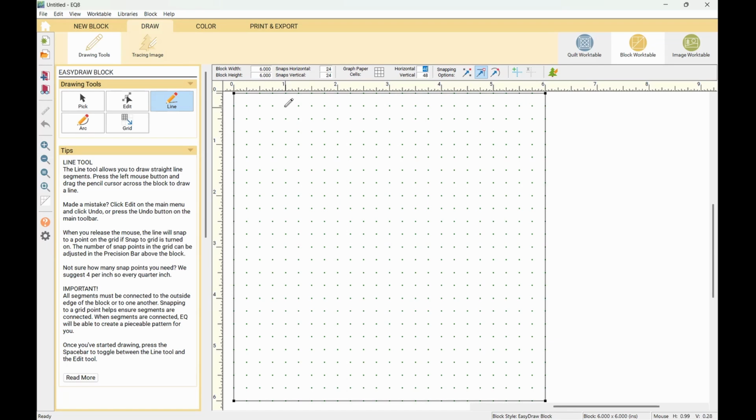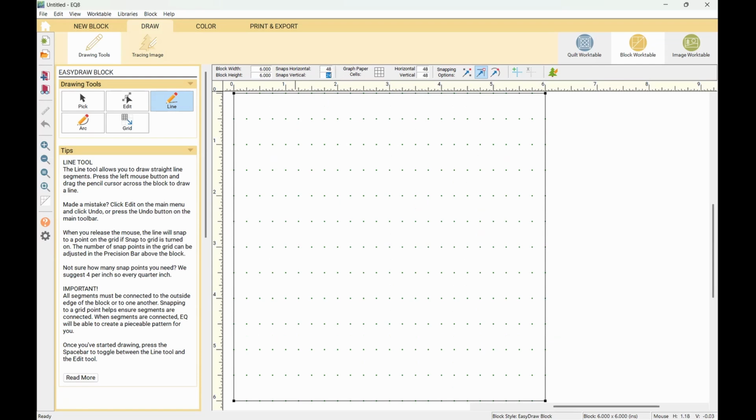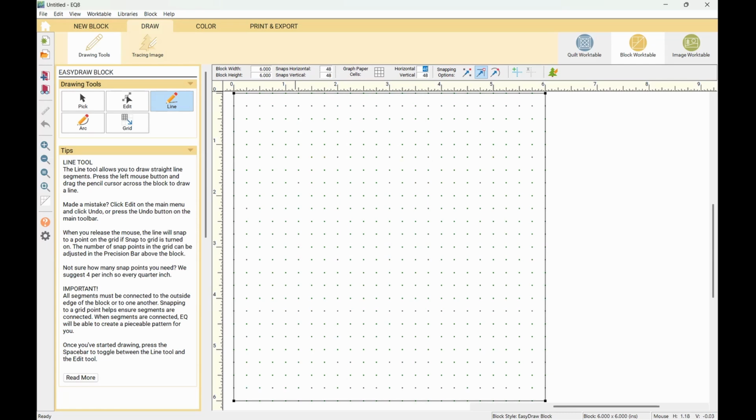And then if you have made it for more, like if I go twice as much, I go to 48, you still see what looks like 24 snaps, but there are hidden snaps on each of the 1/8 inch now versus the 1/4 inch. And it will snap, if you turn on your snap to a specific place, it will snap to that 1/8 inch.